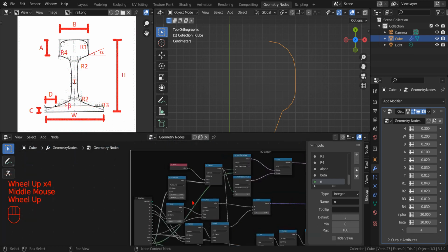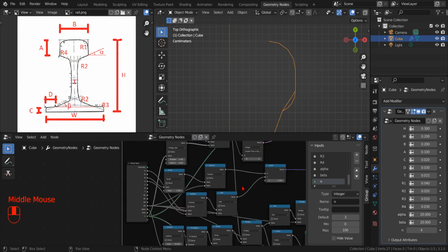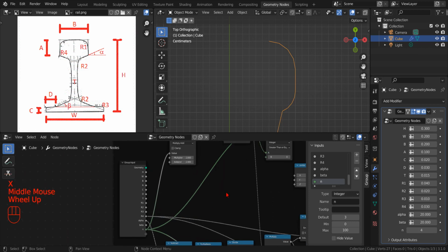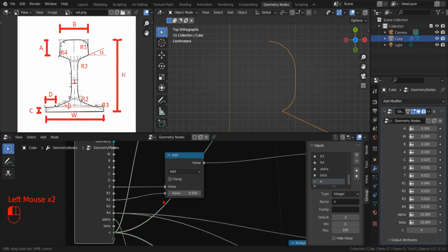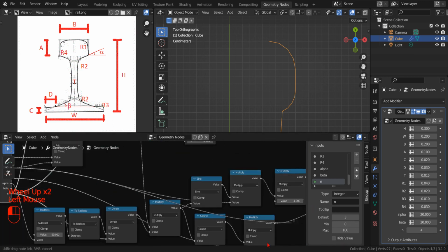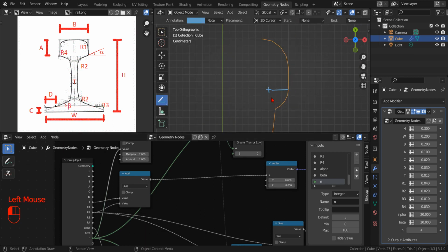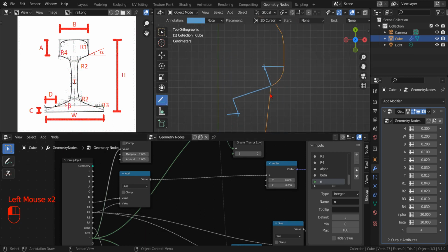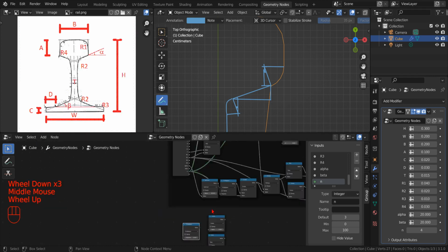The first step is to account for the number of nodes that have already been set in the previous nodes. Then we need to set the new coordinates of the center point. This time we need a lot more than some fancy math, so we sketch the geometric problem to define the y component of the center point, so we can come out with the solution. As we can see on the sketch, these three triangles are similar and have one angle of 90 degrees, and the smallest angle is alpha.